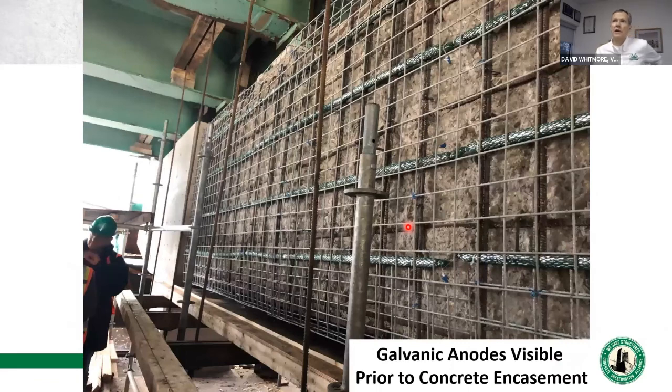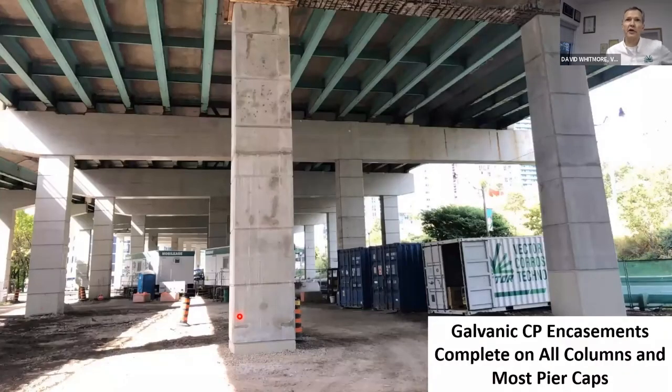And here's a picture kind of during construction. You can see the concrete cover's been removed down to the steel. The galvanic anodes here are these horizontal strips that are in here. There's a layer of galvanized welded wire mesh there for crack control. And the section is formed and poured back. You can see a section of the pier cap here is poured, and this section is being formed, but is not yet poured.